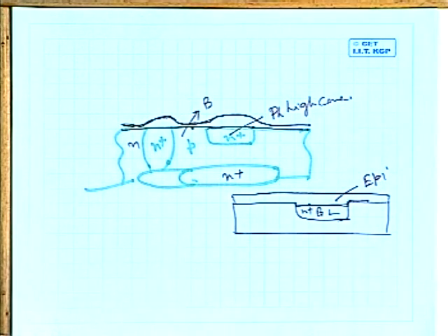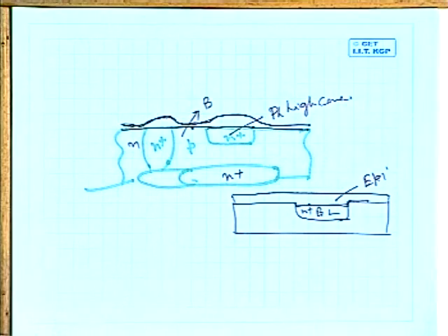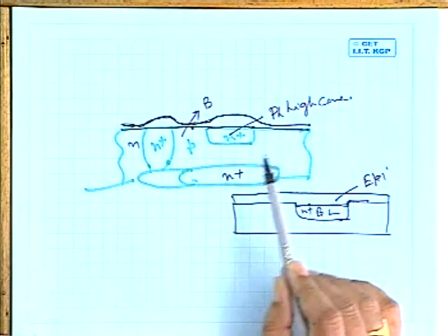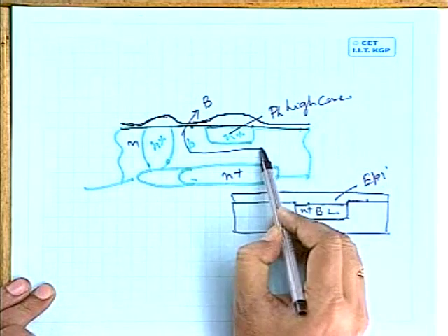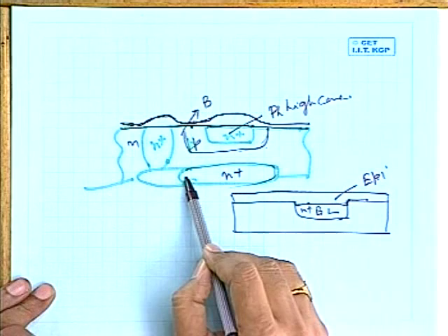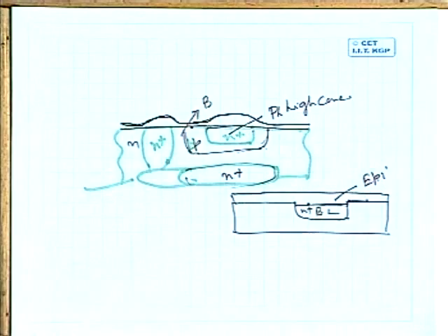As you are growing the epitaxial layer on the silicon surface, then in the subsequent process, how can you see where the buried layer is? Because inside the buried layer, again you have to grow the deep collector or the extrinsic base or base, emitter, etc. This base you are going to align inside the buried layer, and the emitter you are aligning inside the base. So for the subsequent alignment process, you have to identify the location of the buried layer.